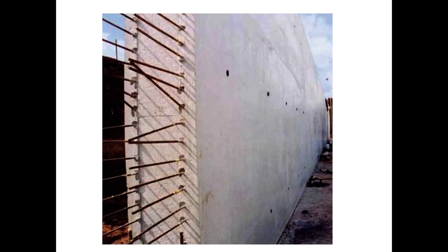Concrete, when you take the shuttering away, tends to take the imprint of whatever the shuttering was. And again, we'll go into that in more detail when we look at concrete. But what you're looking at here is the rebars, the steel reinforcing inside the concrete. This is a load-bearing concrete wall, and it's very shiny, isn't it? It's very shiny, very beautifully polished. So this is actually a kind of concrete which is called self-compacting concrete.